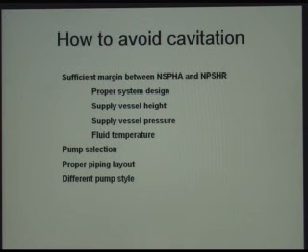If you have an installation, you already have the pump, you have all the piping there, and you do know you have cavitation. How do you overcome that situation? You have to change the pump, or you can change the piping, or change the process? Well, there's a couple of alternatives, and we'll talk about that in a few minutes. But you're right. We could possibly change the piping.